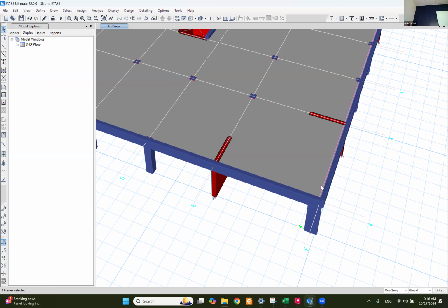By the way, because I'm explaining it, it takes some time, but when you have it assigned, add column object, add wall object, add beam object, it's got it all done. If something is not correct, you can go ahead and change it correctly. Then you assign the load, replicate the story, and it's gonna be a piece of cake. Right? Do you have any questions?